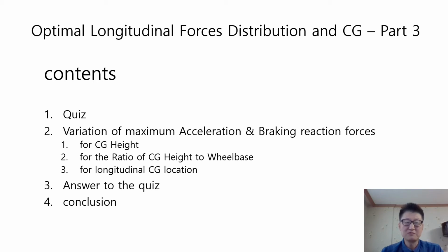In this video, I will highlight the role of CG location by explaining how it changes the maximum longitudinal reaction forces. If the maximum longitudinal reaction forces change, the optimal force distribution curve also changes accordingly.